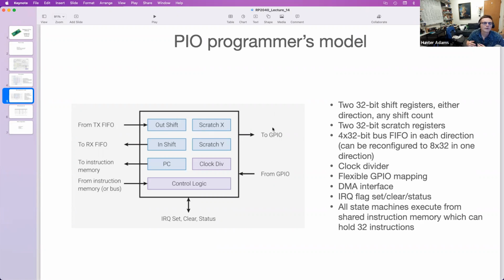This is what I mean. The places from which data can be moved to and from in a particular PIO program include the 2 FIFOs, the 4 registers, and the pins. And a large subset of these instructions just move data from one of these places to another one of these places. With a few details to keep in mind, like some of them allow you to move a certain number of bits from one of these locations to another one of these locations. But okay, we can come to those details in a bit.